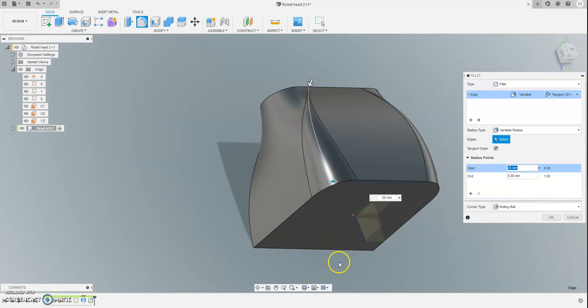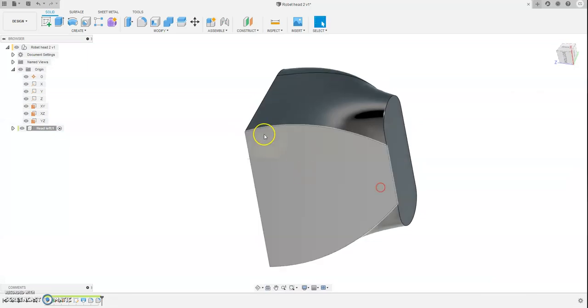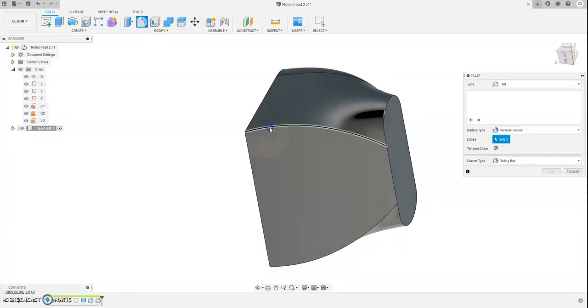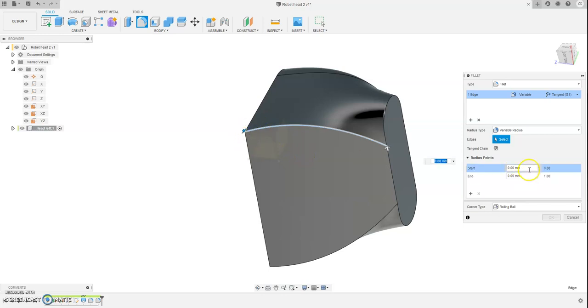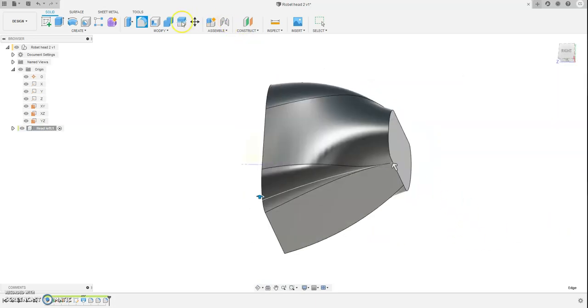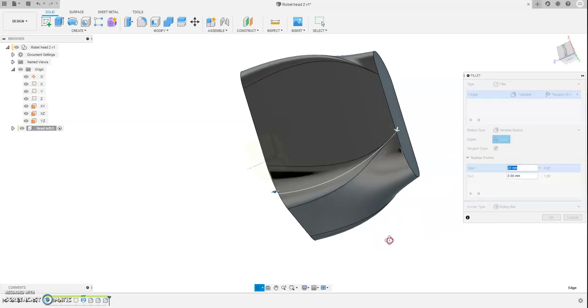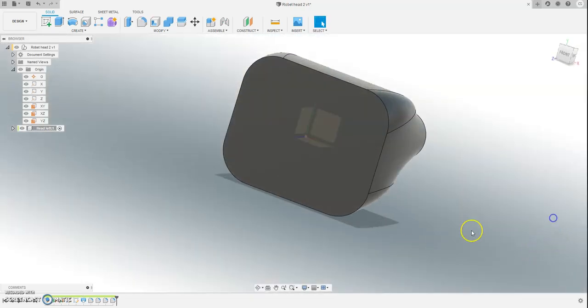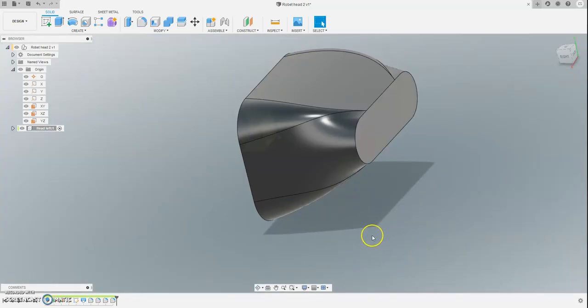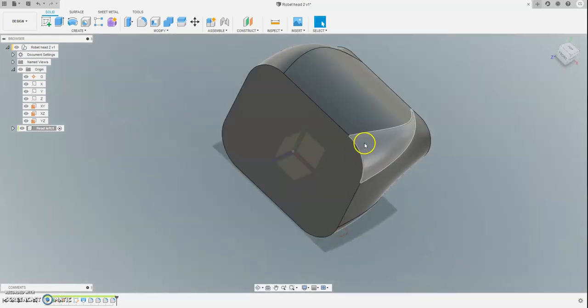Now I don't think I can change select edges now, so I have to do these 1 by 1 with this. Now I think I'll put the same fillet on there. Hopefully it'll generate it. Let's have a little look. There we go. So I'm happy with that. If we look at that, that's actually 2 of our techniques that we need for our Advanced Higher. Now we're looking for, I think it's 5, but we've got the loft and we've got these fillets.